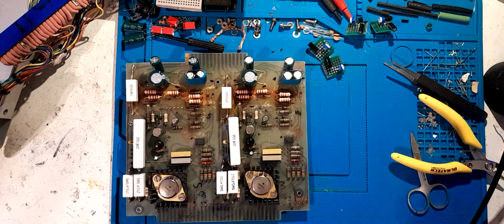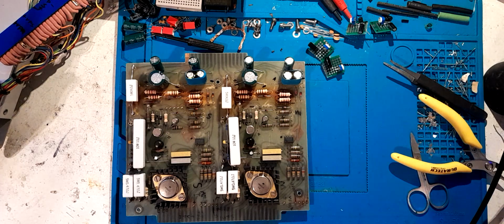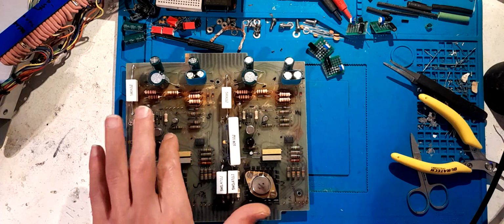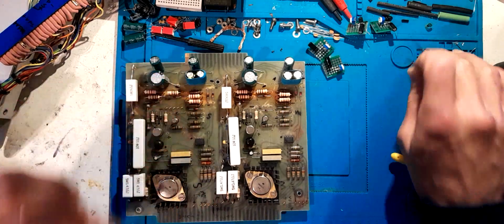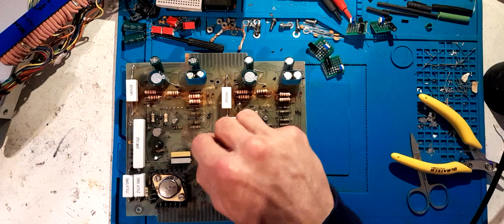Well, first thing I'm going to do is work out, basically under the conditions it's already under, just try and make the TL431s quieter without going too crazy high in capacitance, because like I said, it'll screw things up when it gets turned on and the reference doesn't charge up quick enough. Essentially making it a low voltage reference, lower voltage than what it's supposed to be. You all know what I'm trying to say.